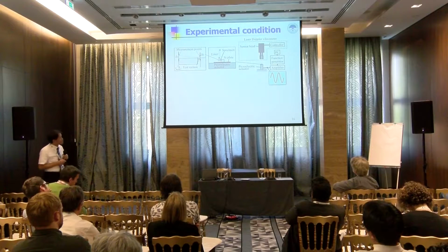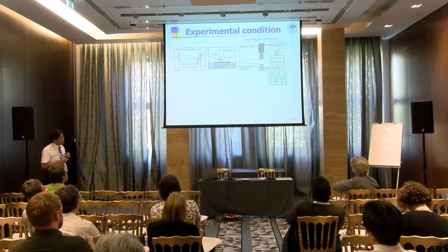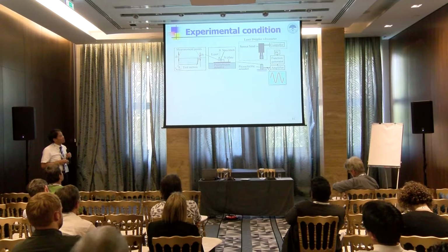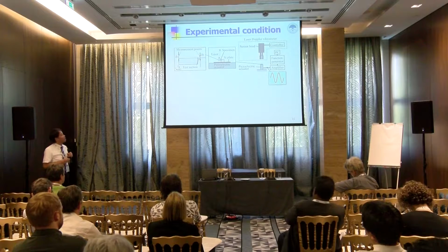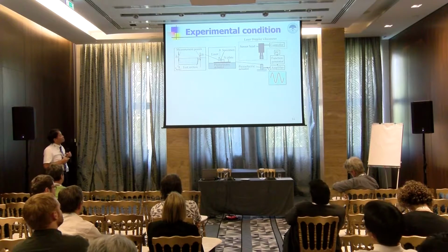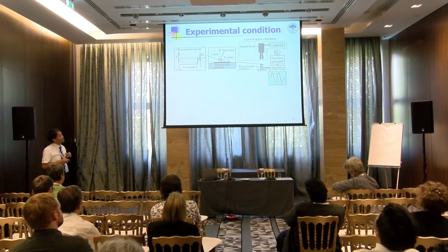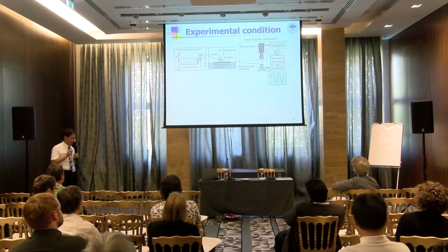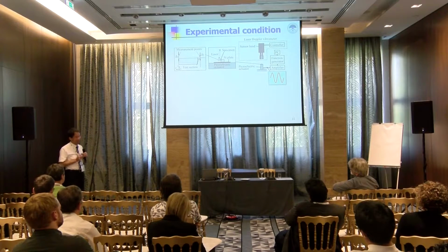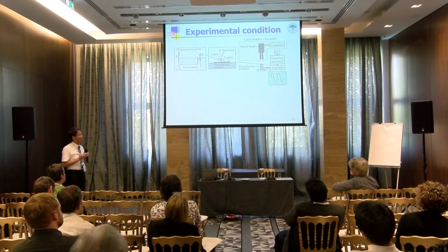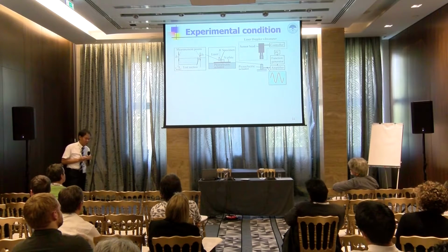Okay, so this is an experimental system, and sine wave oscillation was applied to the specimen by controlling the input voltage to a piezoelectric actuator. And the deformation amplitude was measured by a laser Doppler vibrometer. And so using the resonant frequency preliminarily obtained, we performed a fatigue experiment under constant deformation amplitude.